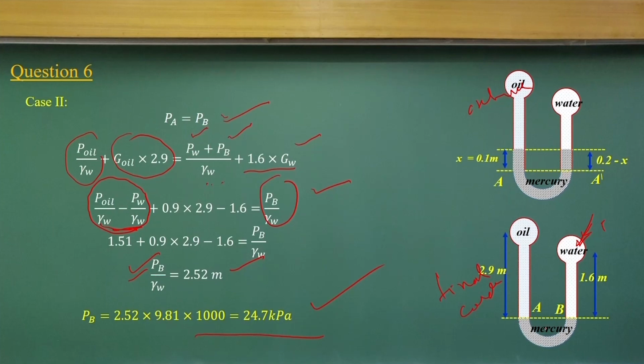We have only applied the very basic equation that on a horizontal surface, whenever you take it, the same pressure acts on that horizontal surface when fluid is at rest. That is the condition we applied to compute the additional force acting on the water to make the mercury level perfectly horizontal.